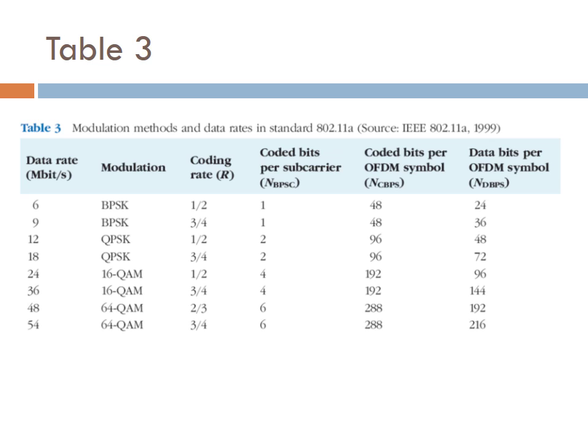Column 5 gives the total number of coded bits per symbol. As mentioned above, in the context of OFDM, a symbol is a unique combination of subcarrier signaling states. The number of bits per symbol is the total of all the bits carried by the subcarriers. Column 5 refers to the number of bits per symbol that are actually transmitted.